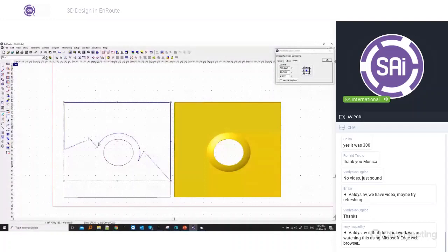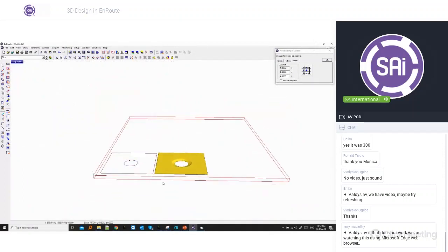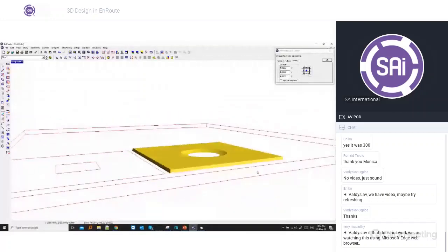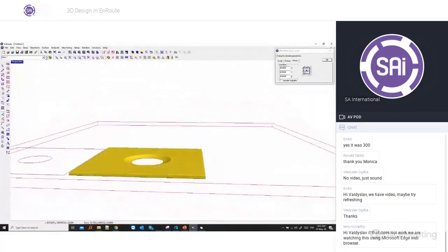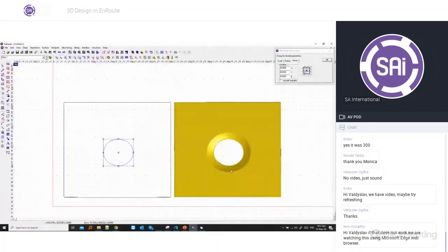So I can now use these contours to create the toolpaths, because as you can see, we would only have to route a part of this STL file or a part of this relief as a 3D object. So the flat part we can just route with an end mill in 2D, and just this edge we would need to route in 3D. So what I would do here is I would simply measure this, how much this is, so about 20 mil.